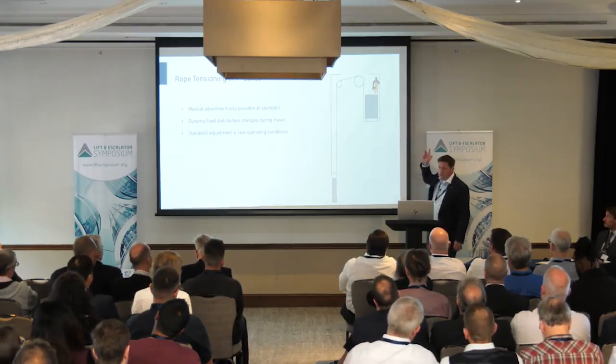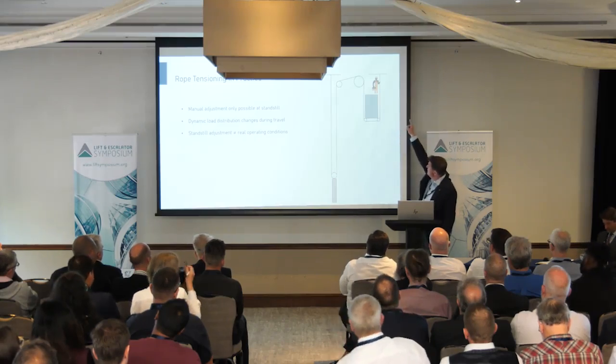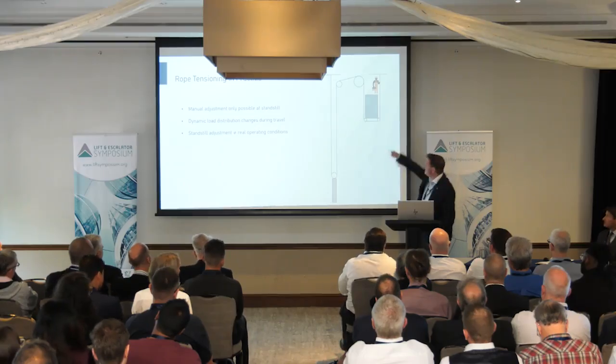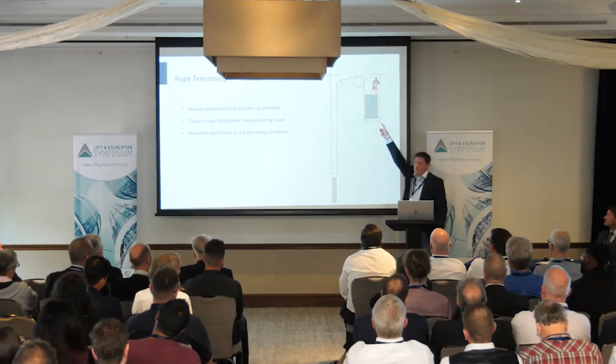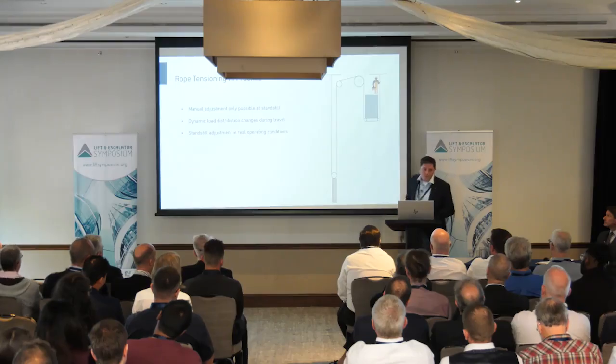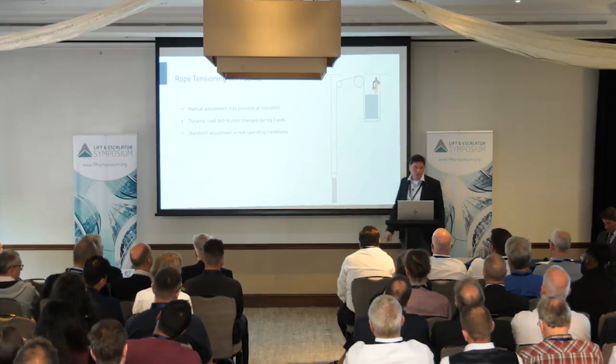If you have steel wire ropes, he's tensioning the ropes between the fixed point and the traction sheave, and nothing else. If these are plastic-coated ropes or belts, he's tensioning just a section to this pulley and nothing else. So tensioning 4 meters of ropes, or 6, and assuming that that will be great for the whole lift does not work. And that is what we see.